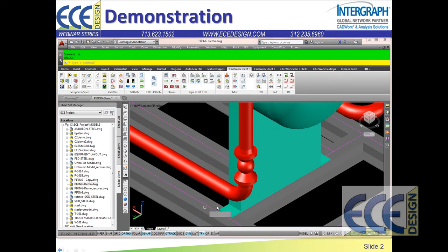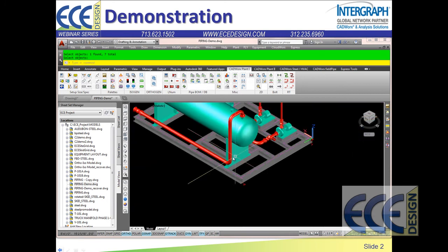So I'm going to go ahead and erase that flange ball valve too, by the way. So make sure I leave my elbow. And one of the rules I had turned on was for it to heal the pipe. So when I erase that valve, you notice the pipe healed back up to the elbow automatically.